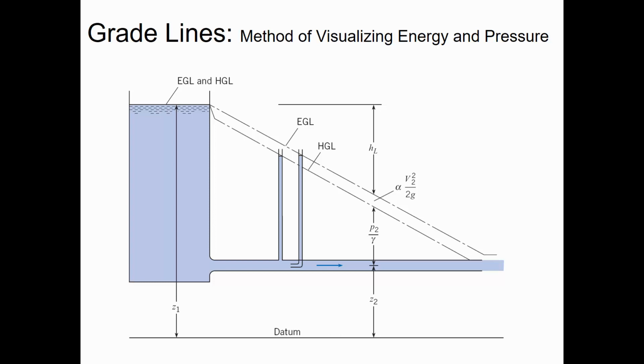And so there's a reduction in the HGL. Like the HGL is diverging. It's below the EGL. And the difference between the two is the magnitude of the velocity head. So you can see it saying V squared divided by 2g. So we've got two locations, location 1, location 2, and they're saying that the distance between the EGL and the HGL, like the gap between them if we graph them, is just the velocity head, how much energy there is.